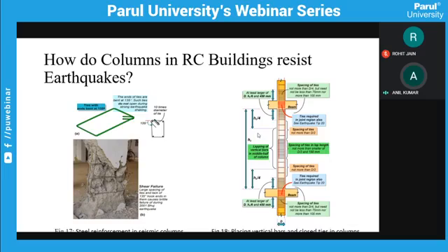And at the portion where the joint is there, at least the larger dimension D, or H by 6 of the height of the column, and 450 mm. Out of these three, whichever is the largest should be this height, at the top and bottom of this beam joint portion. This is the D. Whatever we are telling here is D by 2, D by 3. So this is the D.